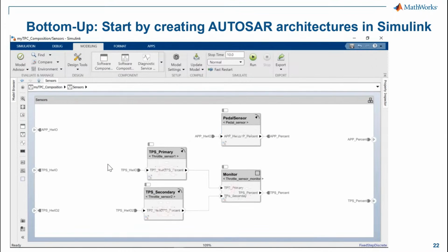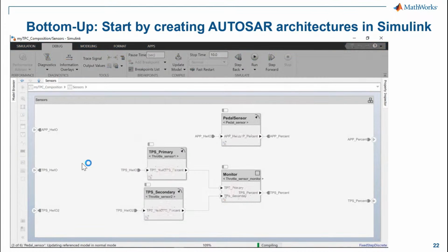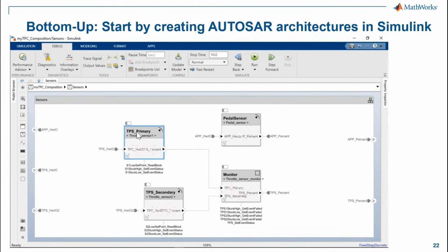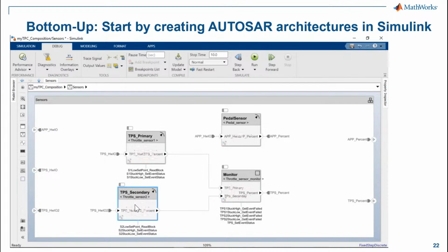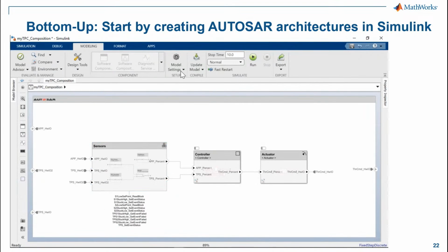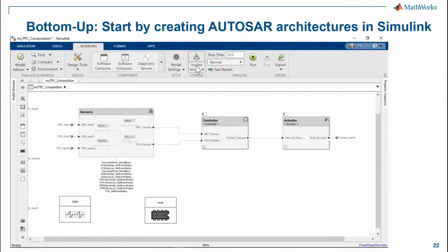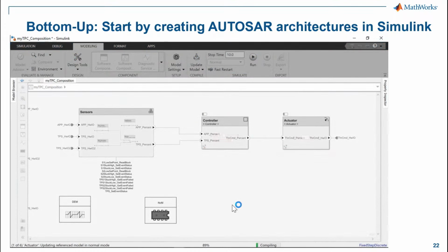Yeah. Great. Okay, now the natural next step is simulation. Before that, I would like to enable the functional connections. That means this model may have calls to the basic software services related to the NVRAM or diagnostics managers. I see that there are connections. It is looking for the reference implementations. So I am dragging the diagnostics services reference implementation and also the NVRAM. Okay, by updating the model, it will make the necessary connections.